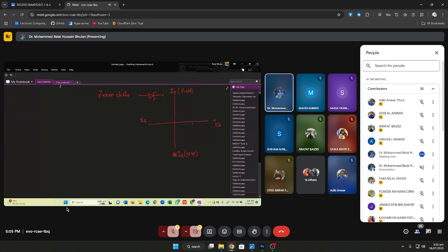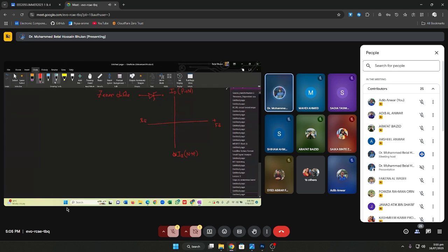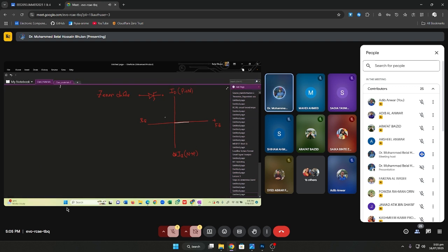Now I'm not going to draw the real IV curves, rather I'm going to draw the constant voltage drop model. In the IV characteristic, it is 0.7 volt forward bias if it's made out of silicon. Interestingly, for reverse bias, it looks like this.